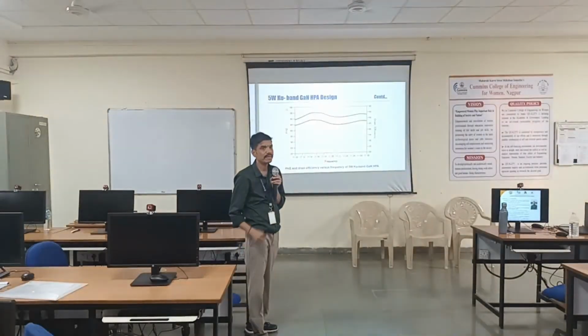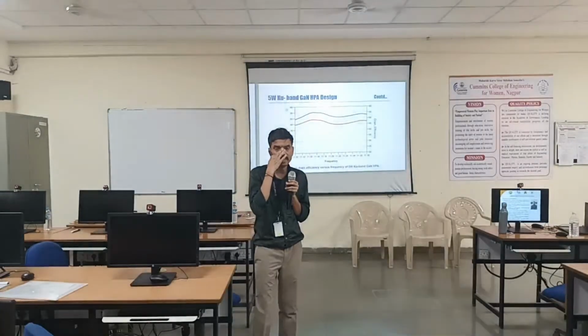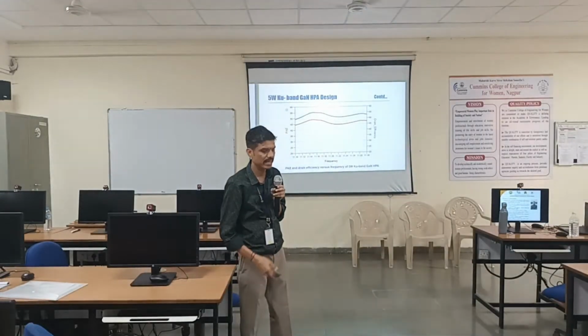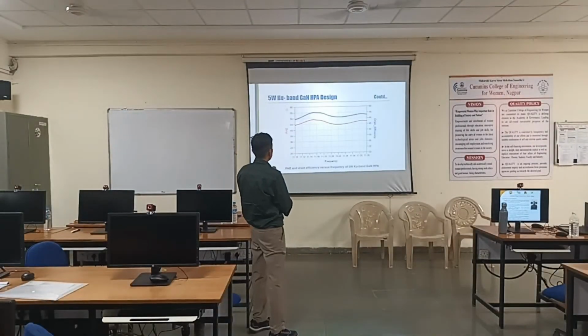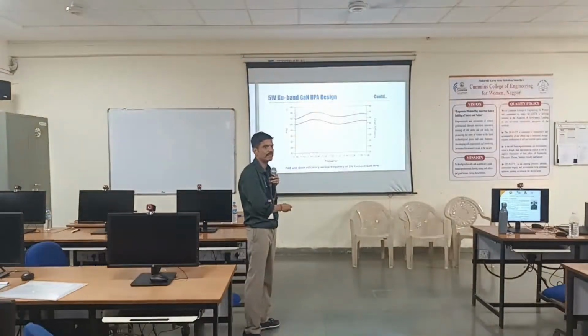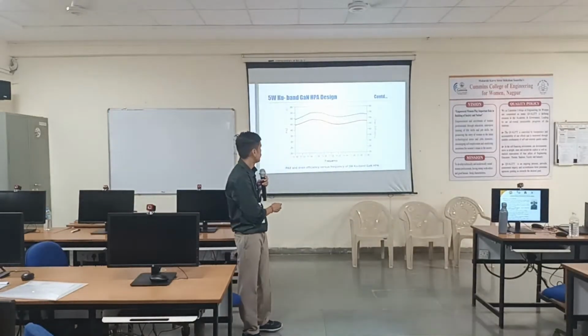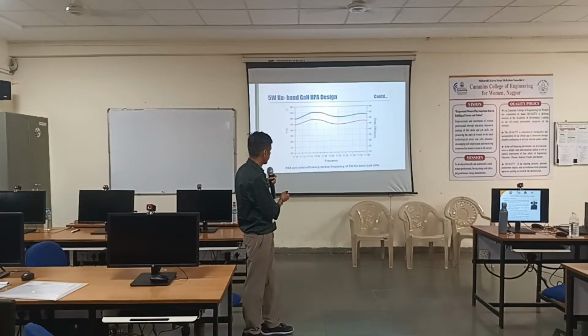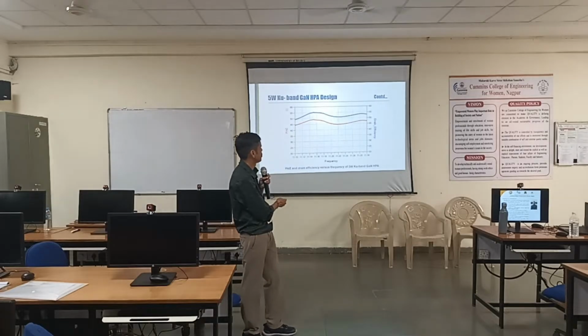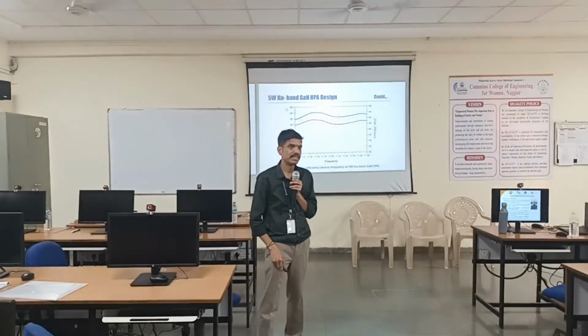Yeah, drain and power added efficiency. As I said, drain efficiency is always higher than power added efficiency, but the more meaningful number is power added efficiency. So we should see we have met the target of power added efficiency more than 55%, but that is for a very limited range. Even we met the drain efficiency only close to 55% for certain frequency, but for the rest, we could achieve more than 45% power added efficiency throughout the band of 200 megahertz.